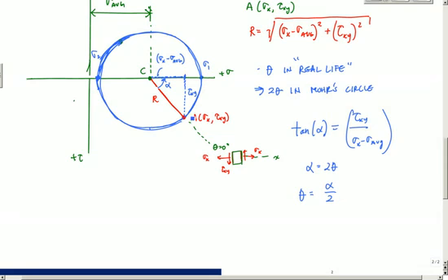So if I wanted to go to the sigma 1 orientation, the maximum principal stress, we're talking about an angle of rotation of alpha over 2, or theta, and here we went counterclockwise. So this original x-axis that was here, we are going to draw at an angle up here. This angle right here would be alpha over 2 or theta to get to that sigma 1 face.